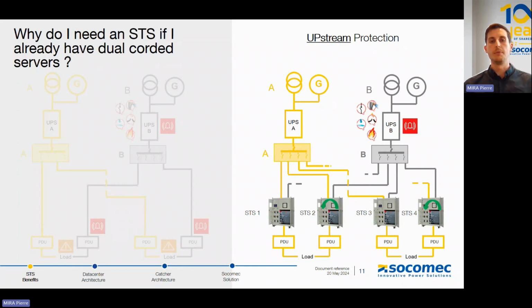Of course, there will be a report on the UPS and on the static transfer switch. The static transfer switch, thanks to waveform capture, will be able to see the timeline of when the error happened, but will still manage all of the power upstream in order to have very safe PDUs providing power to the load. So when we have any upstream event on the UPS, on the switchboard, the static transfer switch is securing every single load below it.